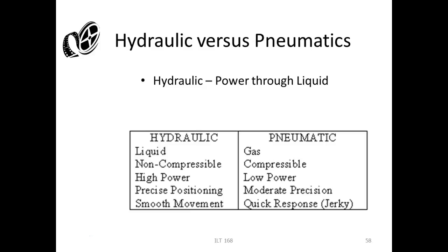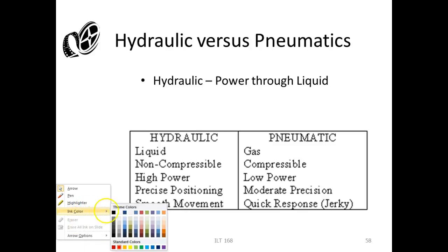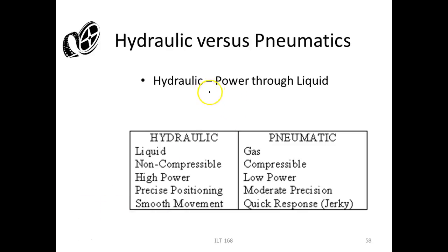The big advantage of hydraulics is that since we use such high pressures, our actuators can be a lot smaller. So, what's the main formula? Force is equal to what? Okay. So if I solve for area, area is equal to force over pressure. What that means is the higher I make the pressure, the smaller I can make the area, right? You get the same amount of force.